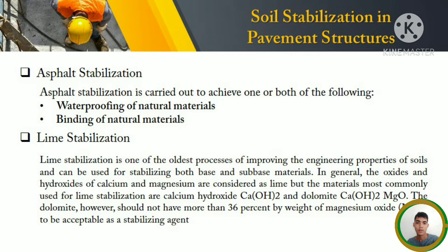So the second one is the binding of natural materials. The binding of natural materials improves the durability characteristics of the natural soil by providing an adhesive characteristic whereby the soil particles adhere to each other, increasing cohesion.